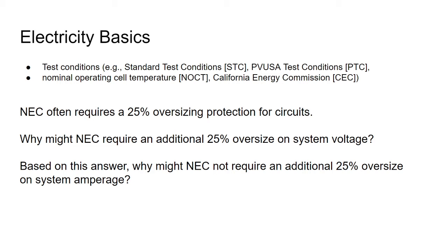And as we saw in our National Electric Code class, there are additional provisions like how many conductors are in a confined space, whether it be a conduit or adjacent to a rooftop. That might say there's more heat in the environment than normal, and so we have to derate because of heat on top of that.